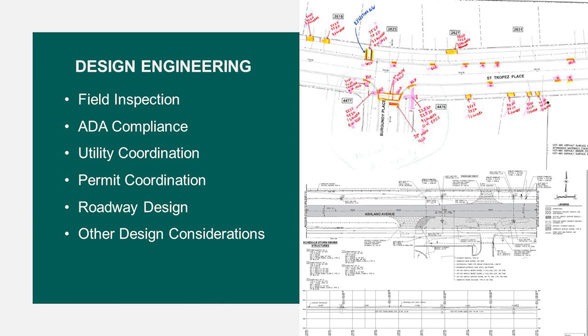On sidewalks, we're looking for trip hazards. A lot of municipalities have their own criteria for how much they're willing to replace, what condition, how many cracks in the curb there are. Then there's also ADA compliance. I'll be speaking a little bit more about that.